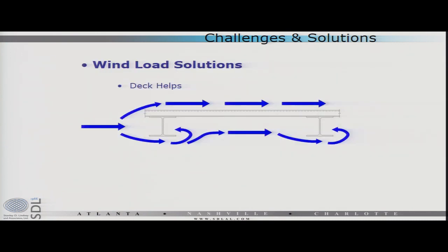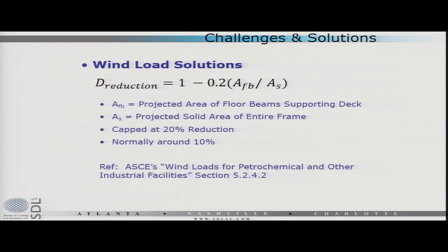Also deck. Deck helps. A little, right? Not a lot. So you would think that once you put the deck on, it's great, but the wind still gets up under there, and there's really not a lot of research in this department. I think it's a place where we can get a little more out of it, and we just haven't done it yet. The actual reduction is documented in Wind Loads for Petrochemical Facilities.